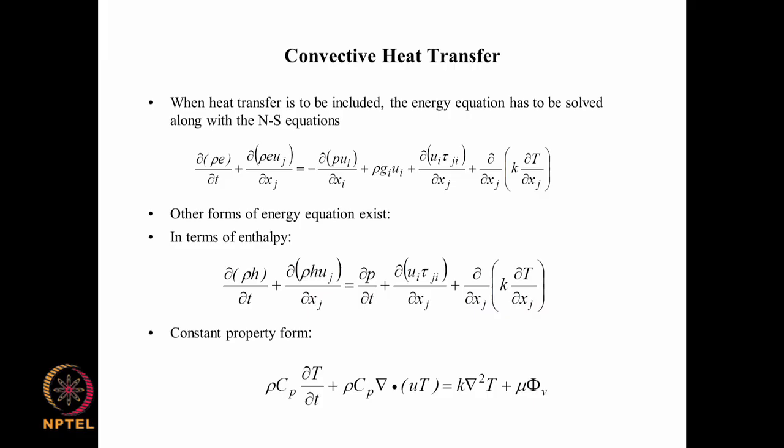And from that you can compute the heat fluxes through the walls, and from that, if you still want, you can get some idea of the heat transfer coefficient. But if you are directly getting heat flux, then the heat transfer coefficient is not necessary to be computed in the CFD solution. It is a post processing thing. If you want to find out the heat transfer coefficient, then you can do that.